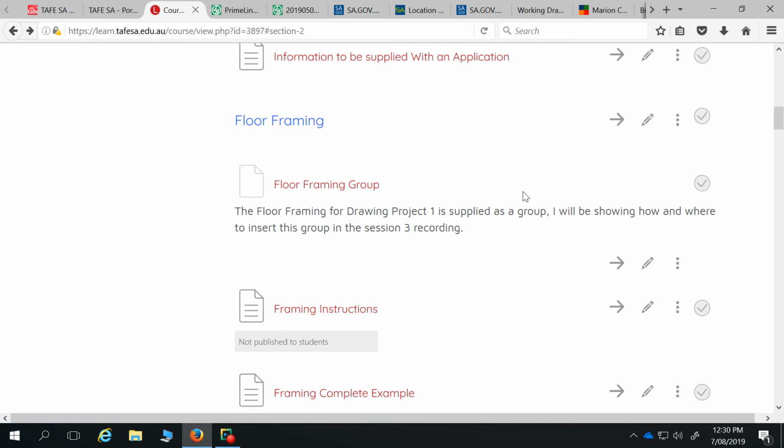We can change that, and then set up your ceiling level at 2.4 or 7. I don't even remember. It's been nearly 6 months since we did this one last. But it's in the specs. Draw your walls and everything, and then when we get to it, I'll show you how to import this floor group, so all the floor framing will come in for you underneath. So that's there.